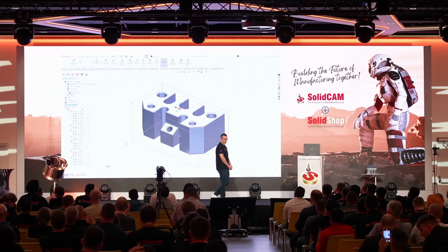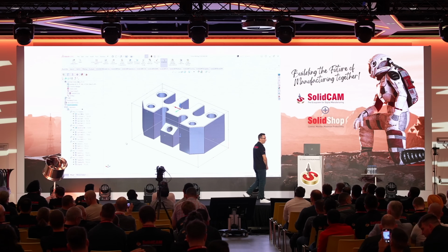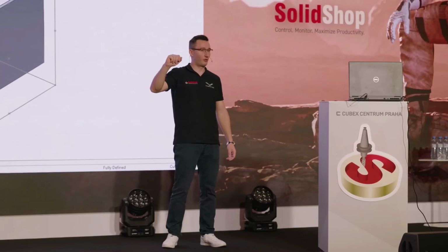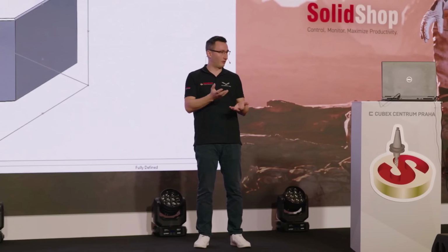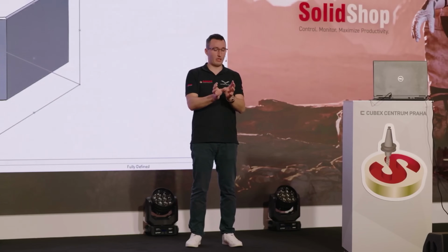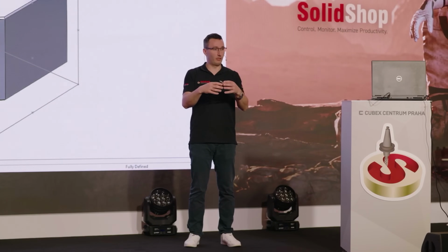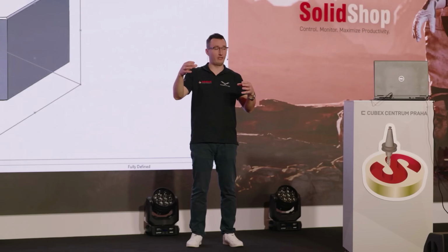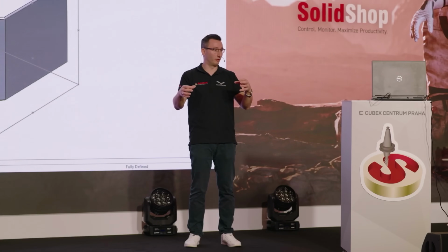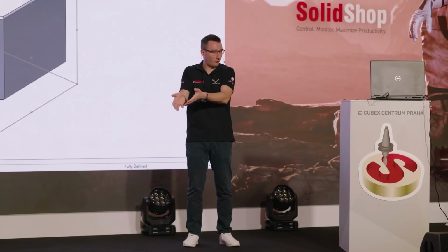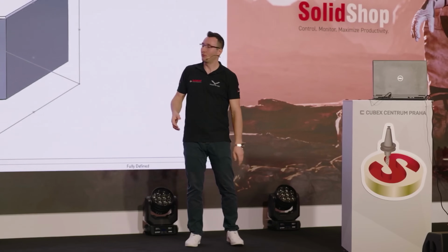Here is where things start to be interesting, because you can see those are not calculated jobs. So you are thinking, why do I need to calculate it? I already had the toolpath. This is the perfect scenario where I had the part with the same fixtures, positioned the same, sure. But what if I take one part and make it lower? If I use the fixture protection, the toolpath for that workpiece will not be the same. So let me show you that.